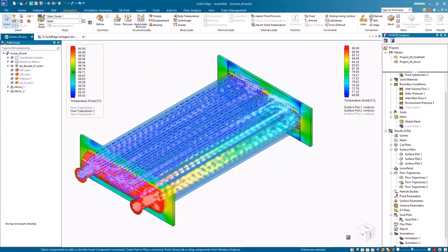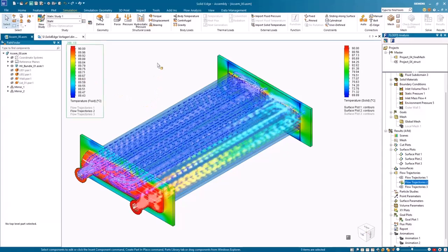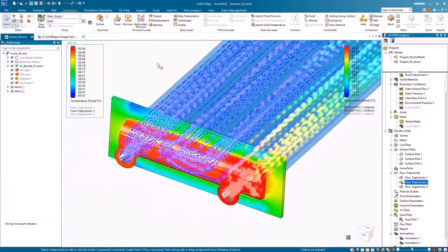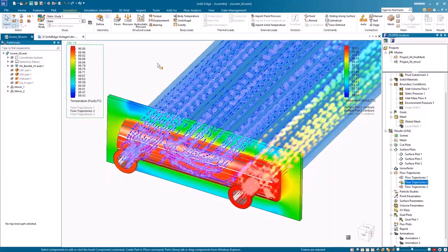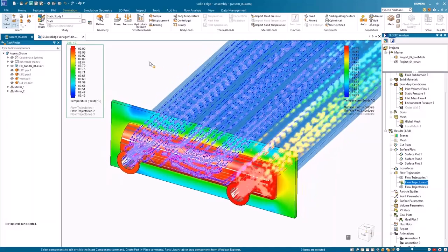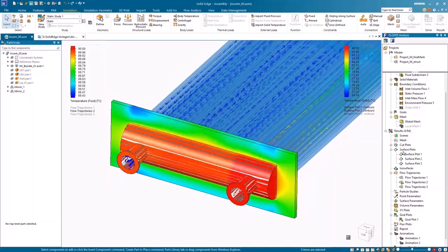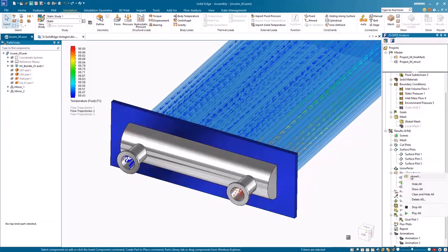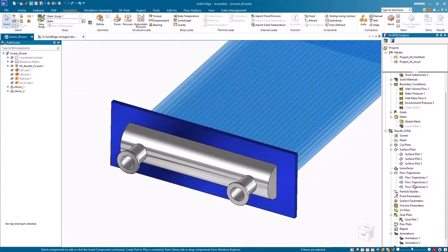Increase your simulation speed, performance, and reliability with new enhancements in Solid Edge Simulation. Instantly import solid temperature results from SimCenter FlowEFD for Solid Edge into a static simulation study with the new Import Solid Temperature command in Solid Edge Simulation. In this example, the results of a FlowEFD simulation in a heat exchanger and the temperature distribution of the fluid flow on the parts are shown here.